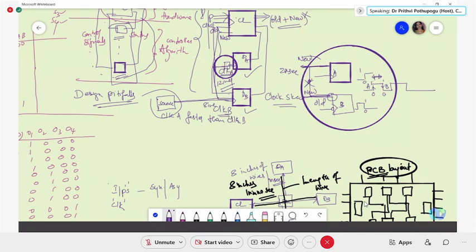When we took the pitfall explanation, these were two different flip-flops having two different sources. One of them is faster and the other is slower. That makes a skew, we were saying. But to come out of that, the source should be common, is the remedy we have given. After you connect, we see that the source is at equidistance. That point of A being faster and B being slower will be eliminated if the source is at equidistance.